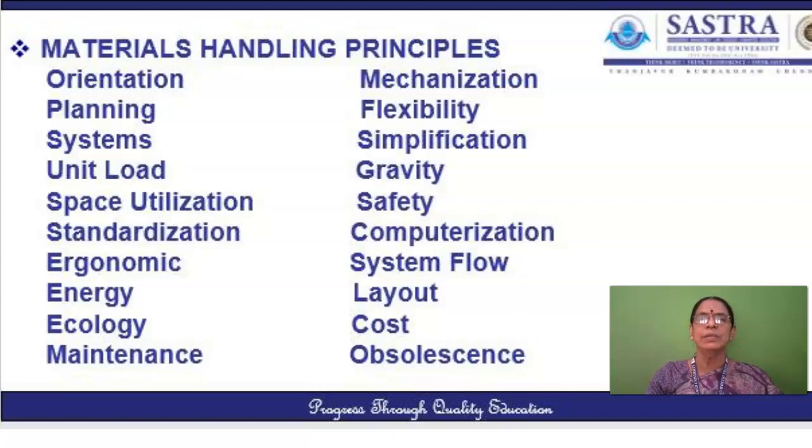Success in planning large-scale material handling projects generally requires a team approach involving the suppliers, consultants when appropriate, and the end-user specialists from management, engineering, computer and information systems, finance and operations. The material handling plan should reflect the strategic objectives of the organization as well as the more immediate needs. The plan should document existing methods and problems, physical and economic constraints, and future requirements and goals. The plan should also promote concurrent engineering of product, process design, process layout, and material handling methods, as opposed to independent and sequential design practices.